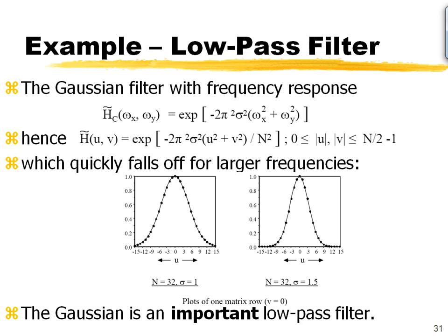Now when I convert it into the digital version, I have to divide it by n squared so that all I'm doing is ensuring that the energy under the defined Gaussian still remains 1. Okay? That is the reason you always will have a division factor in order to ensure that the integral remains 1.